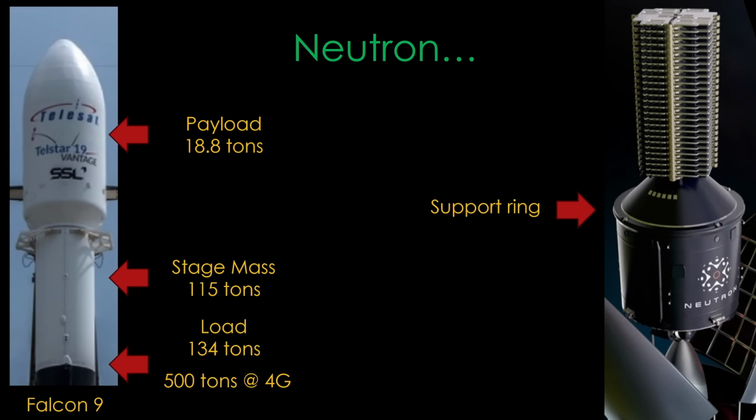And the carbon fiber that is used in Neutron is much stronger under tension than under compression. Both of these mean that the second stage can be lighter. It's this sort of design that makes me unexcited about the other companies that are mostly building Falcon 9 clones. Rocket Lab is leveraging their deep experience with carbon fiber to create an architecture that is better than Falcon 9.